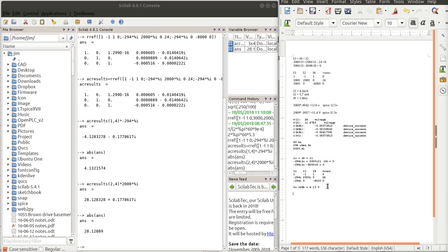And this is pretty common in AC circuits, particularly if you're mixing capacitors and inductors, that you could actually have voltages that appear to be greater than your source voltage. So my VL is equal to 28.12. We'll just call it 28. We'll make it 13. That way I'm consistent with my decimals. Okay, so I'm going to save this.